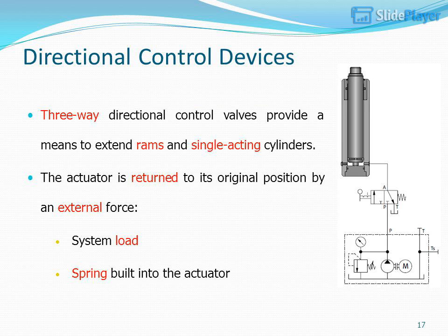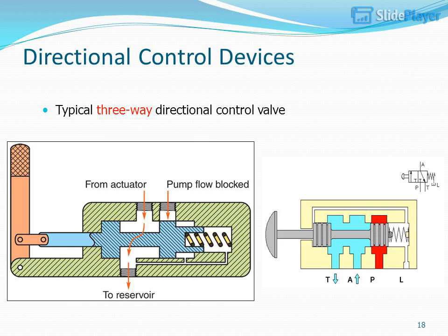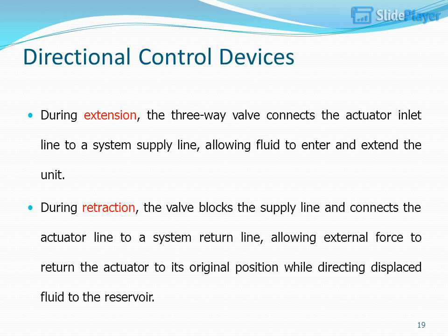Three-way directional control valves provide a means to extend rams and single-acting cylinders. The actuator is returned to its original position by an external force: system load, or a spring built into the actuator. Typical three-way directional control valve.